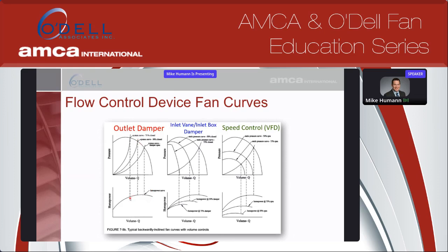And you can see with horsepower, you don't have as large of an effect because you're not changing the actual fan curve. You're staying at your same speed. That's constant. And you can see you're just getting a small horsepower savings here. So this is really just to add resistance as needed to help tune the fan for the application.